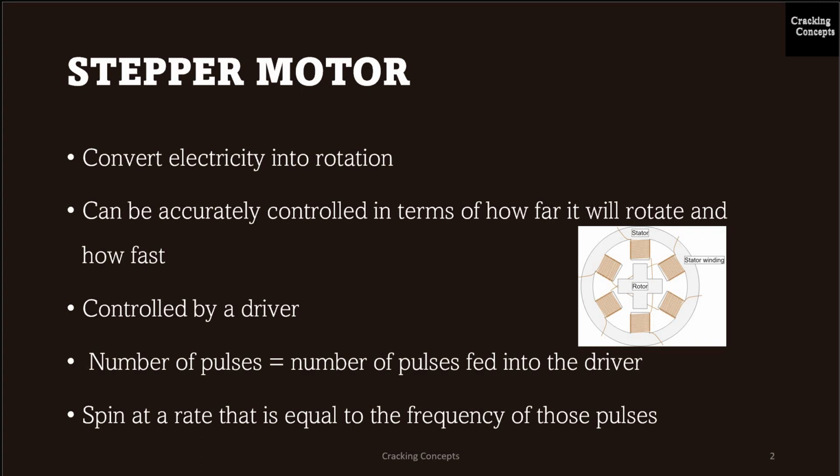Each winding is connected to the winding of the opposite pole so that both poles are magnetized in the same polarity when the current is sent through the pair of windings. The opposing pairs of poles constitute one phase. Here we have a three-phase motor.